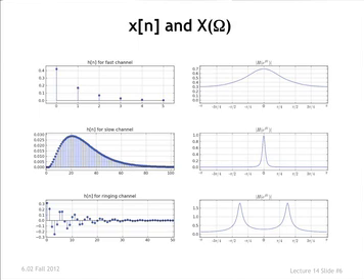Here's another example, a signal that actually seems to have some fairly regular periodicity to it, and then it damps out. By the way, in all these cases, I'm assuming the signal's identically zero outside of what I've shown you here. If you take the DTFT of this, you find that the spectral content is what? Low frequency, mid frequency, high frequency? Mid frequency, right? Because this is low frequency here, 0. This is high frequency. This is just a reflection on the left side. So at some intermediate frequency, there's a peak in the spectral content.